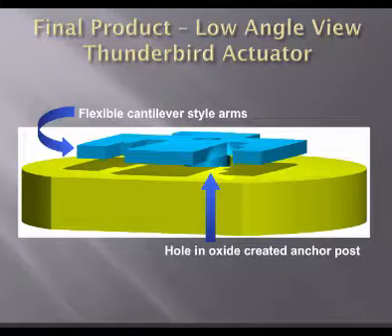So you have to put something else in there to actuate it, right? So in that case, it would be a little bit of a plate or something underneath the wing. So if we did that, then we'd need another layer, right, and another mask and another set of etching processes and deposition processes, right, to make it move.